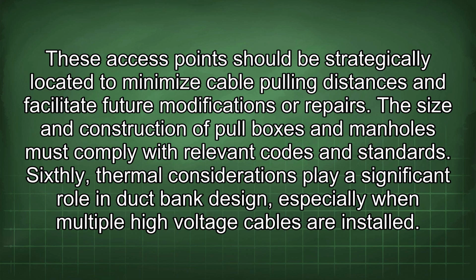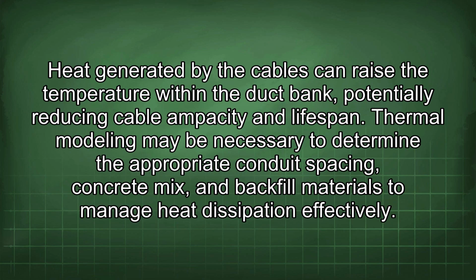Sixthly, thermal considerations play a significant role in duct bank design, especially when multiple high-voltage cables are installed. Heat generated by the cables can raise the temperature within the duct bank, potentially reducing cable ampacity and lifespan.